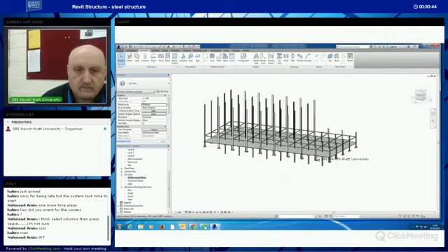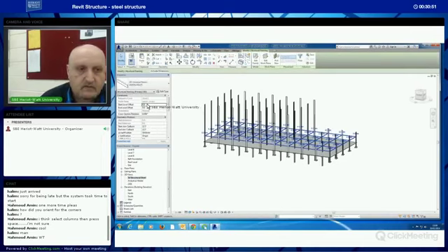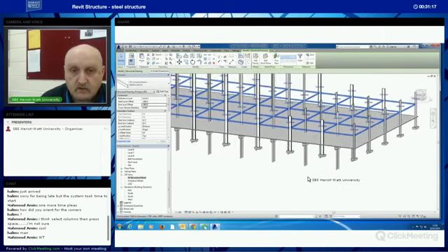So I'll go back here, I'm going to select all of the beams again, select one, SA will select them all. I'm going to give them a start level offset to the value of the thickness of the floor, which in my case was minus 300. It's not always minus 300, sometimes the floor thickness isn't 300, so be careful. Apply, and then these should just pop down. I don't know if you saw that, but they did pop down a wee bit, and the new offset, the negative offset, is visible to you. You can see them in there. If I zoom in, you should see them.